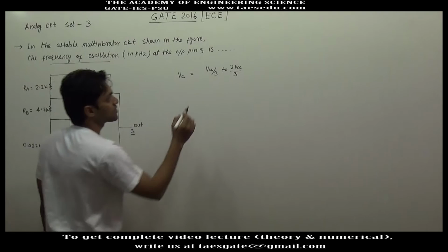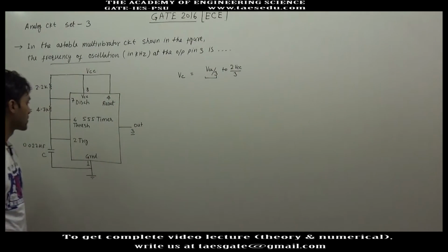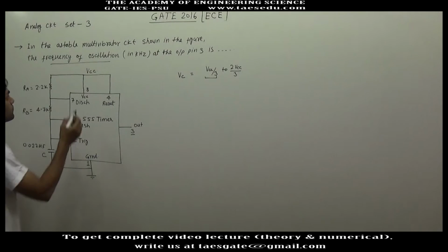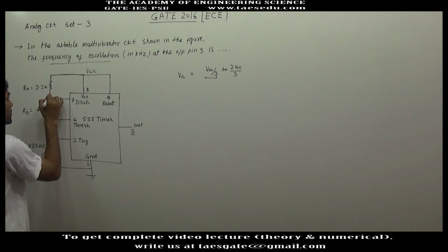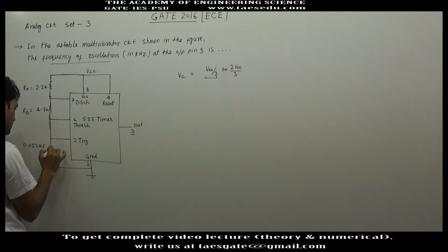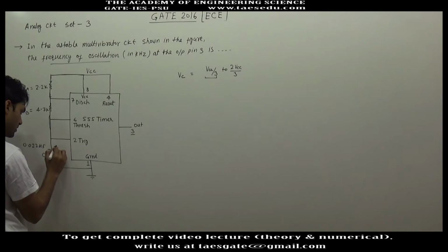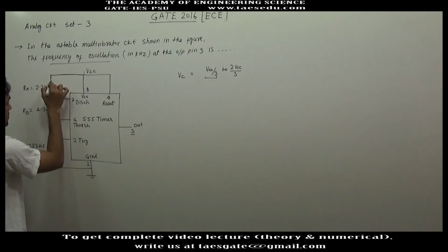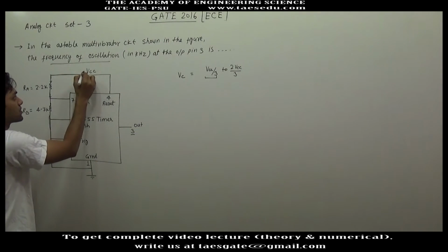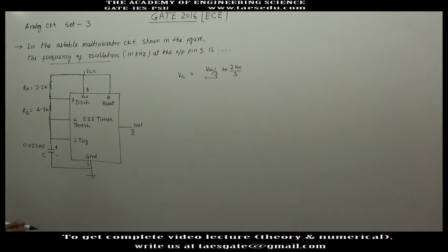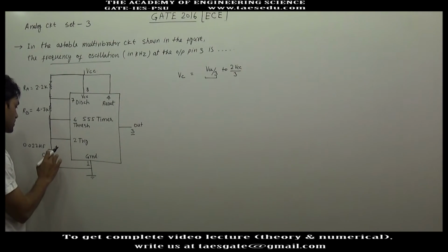When the capacitor voltage hits the minimum value, it starts charging and it charges through VCC. So the charging path is current will flow through RA, then RB, then capacitor, then in this case it will be charged through VCC, RA, RB, capacitor and ground. So the capacitor will charge towards VCC, the steady state voltage of the capacitor. If it is left to charge through VCC for mathematically infinite time, the steady state voltage will be VCC.